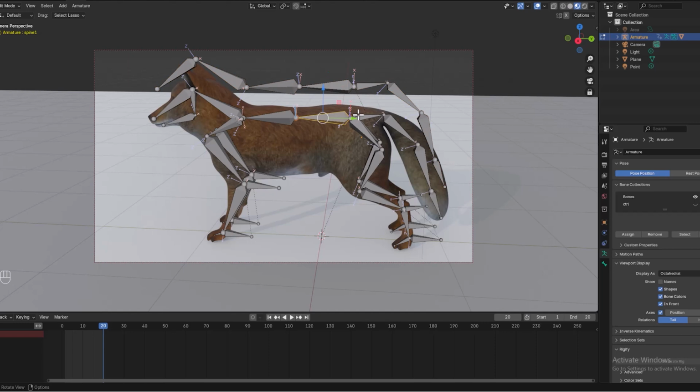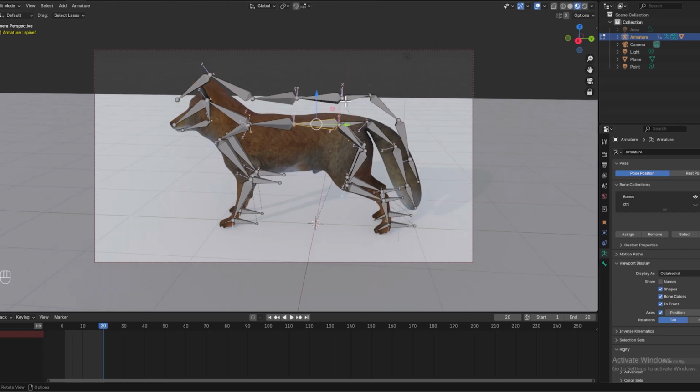For this I want to create one thing here. I'm going to select this bone here and I'll press Shift D and move this one here. Let's unhide those for kinematic spine control. This bone will be our torso control. Let's rename this by pressing F2. We call it torso control.